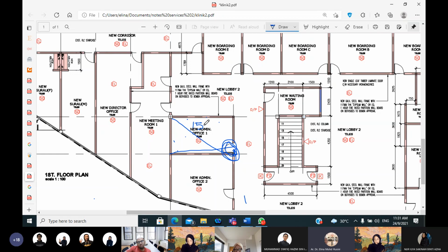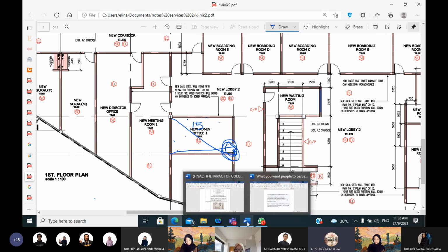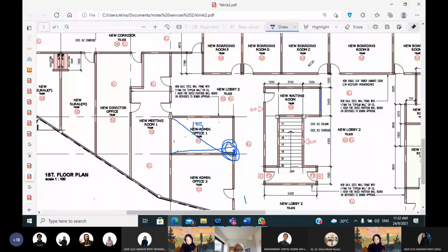But in the section, they allow and allocate this, basically referring to which purpose of category of building, category of room, what kind of design, okay? If dead end, just now I'm showing you the route at the end of the area, there is no more access to a corridor, that one is dead end. So today you are learning what is dead end, and what is the travel distance, sprinkled and unsprinkled. So you learn that.